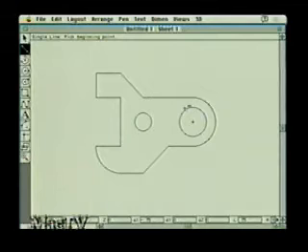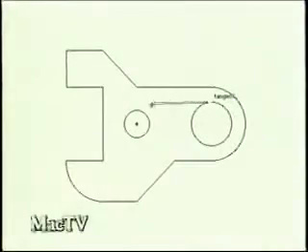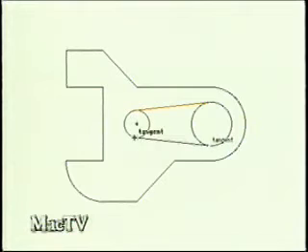I can get on this line and pull a line that's tangent, and it actually stays tangent. As I go and touch this circle, I get all kinds of options, such as tangent. And then same thing here, I could be on and tangent. And as long as I see the word tangent in both places, I know that that's exactly what I've got.